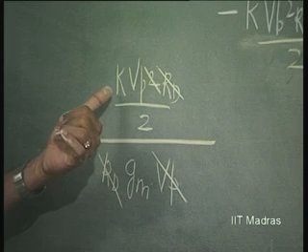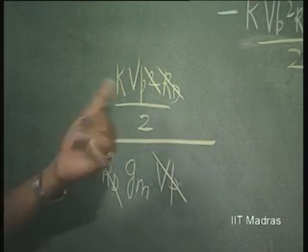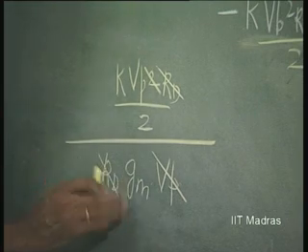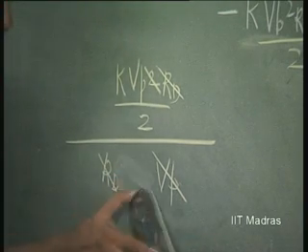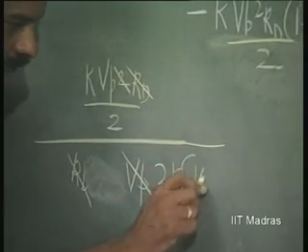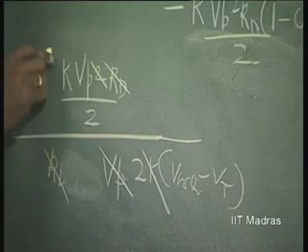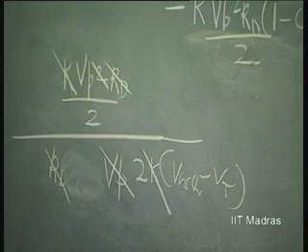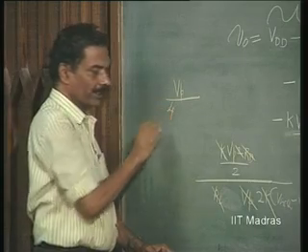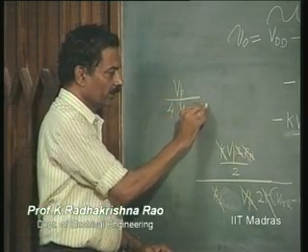Here you are going to do it using this k, the parameter associated with this. So, please see this Gm is really speaking equal to what? 2k into Vgsq minus Vt. So, k gets cancelled with this. So, distortion is really Vp divided by 4 times Vgsq minus Vt.